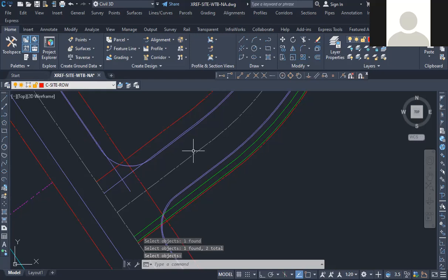Now, see how I have two curves where the road right of ways intersect? This is one road, this is the other road. Road right of ways typically don't end in a subdivision at a squared off corner. There's usually a radius like the road. Okay, so I think I made the road like a 25-foot radius. Look in the ordinance. The ordinance specifies what all this stuff should be, right? But if I fillet this, the whole tail of this line disappears. So all I'm going to do is break this a little bit so that it's two segments.